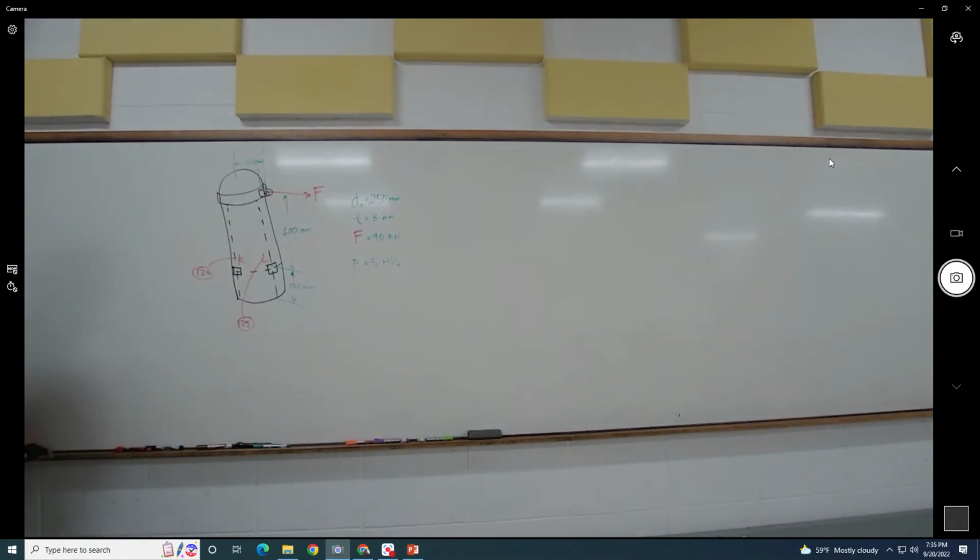The big difference between these is really going to be that L is going to have compressive bending stress. K is on the neutral axis that would be created here for the bending. Can you picture that? Because K would have transverse shear, but not at L. Oh, okay, that makes more sense.